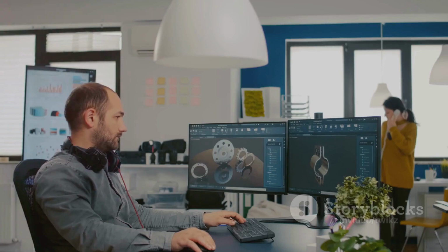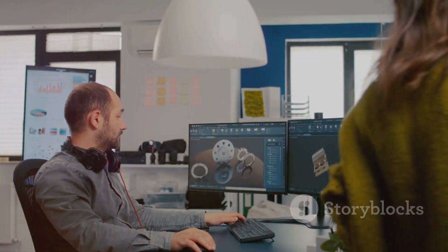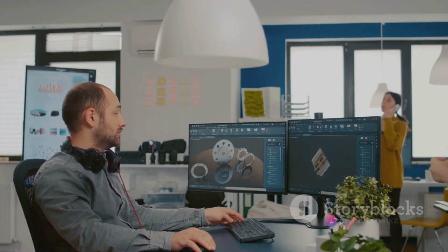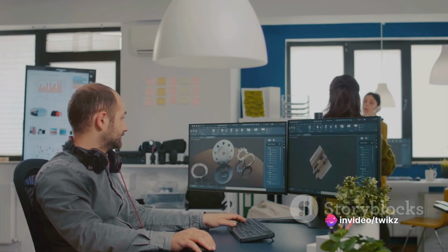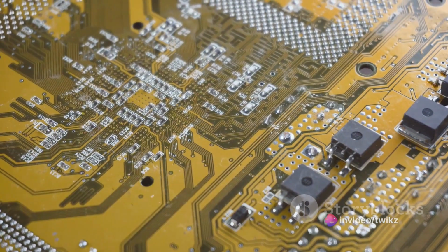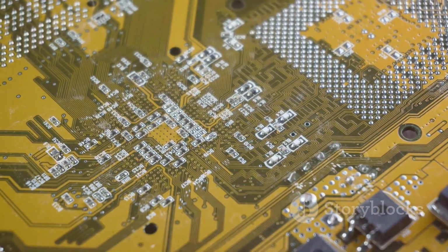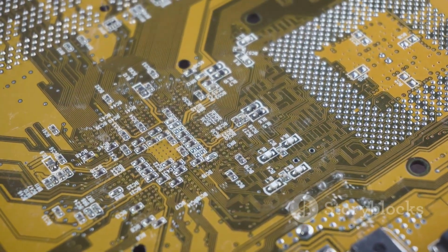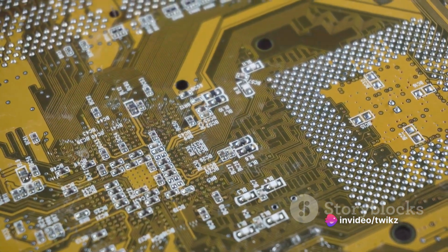Next up is design optimization. Here we optimize the gate-level netlist to meet various design constraints, such as power consumption, timing, and area. This step helps improve the design's efficiency and performance. Finally, we transition to physical design. We place the logic gates and perform routing to create the physical layout of the IC or SoC. It's crucial to ensure that the layout adheres to timing and area constraints.